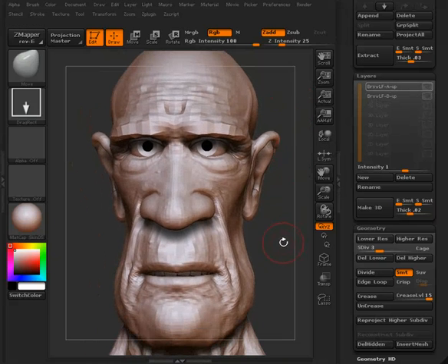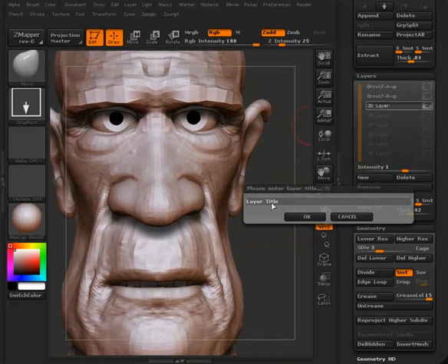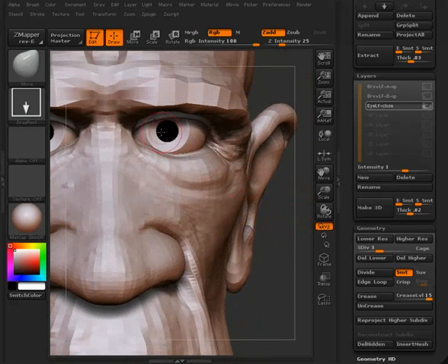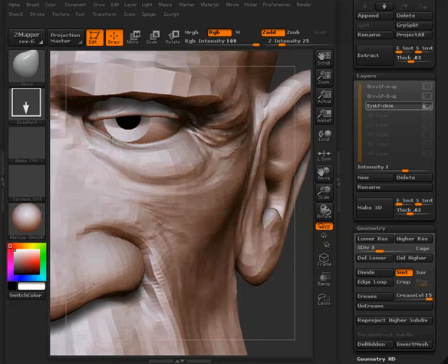Alright, let's go ahead and create some eye shapes. We'll create a new layer and call this one eye left close. This is another one that's going to be challenging here at level 3. More ideally it would happen at a lower level, but we can make it work. So let's close our eye up just by dragging this down, pulling this lid up.